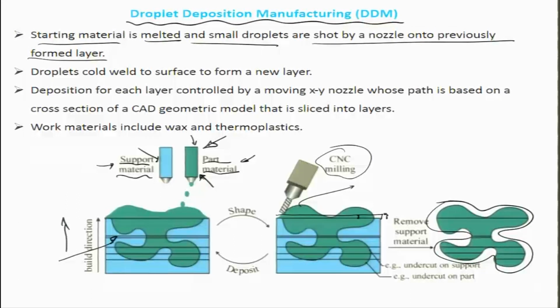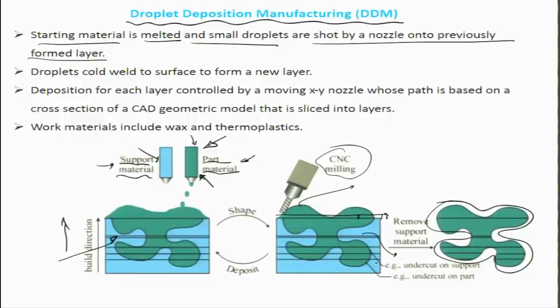Obviously, this is not really a perfect example of additive manufacturing, because it uses a lot of material. If you control the droplet spraying in a certain manner, it may be possible to minimize that, but there is of course a loss and a subtractive aspect to this process. So it is not a pure additive process, but eventually when you get rid of the support material, that is the wax, this particular part, which is otherwise a very complex geometry, emanates as an as-built part, layer by layer.